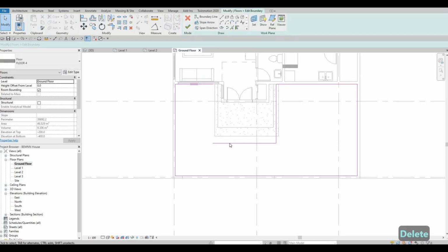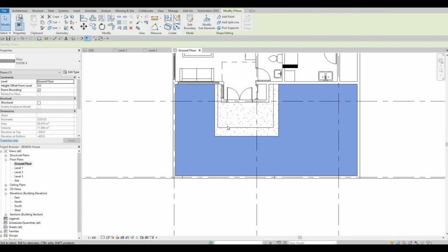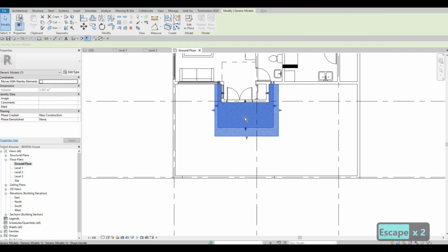What I'm gonna do is, I'm just gonna delete this so that it will be just this singular, and I could edit this depending on how I want this. So that's why I created this as an extrusion, so that I could edit out whatever I want. It's easier to manipulate rather than having a stairs here.